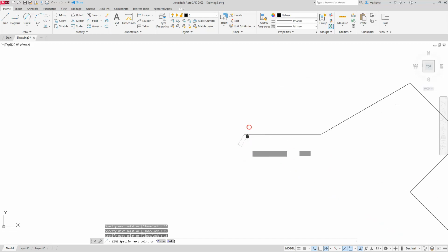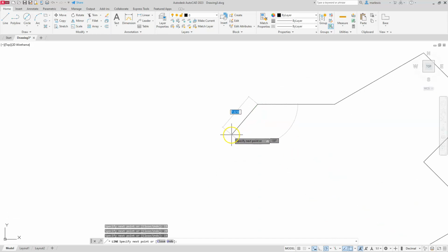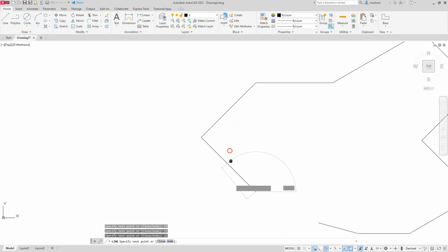Enter. This needs to be at 135, so that's easy. So I can tell AutoCAD to show me that 135 angle there. So I have it verified on there, and that's 15. Once again, I have another 90, which those are nice and easy to figure out in AutoCAD. So I can verify it on the screen. That's my 90. That's going to be 15.